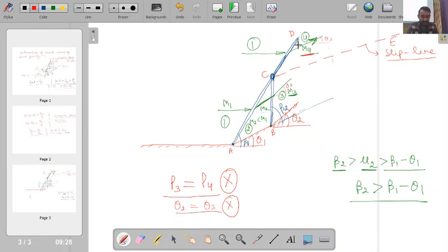I can create some situation where only a single condition can be satisfied when the flow goes after two waves and a single wave, but satisfying both conditions at the same point of time is practically not feasible. So what happens basically, nature itself tries to adjust this necessary condition, and in an attempt to adjust it, nature creates a reflected shock wave from point C. So here I will have, from C to F, nothing but a reflected shock wave.